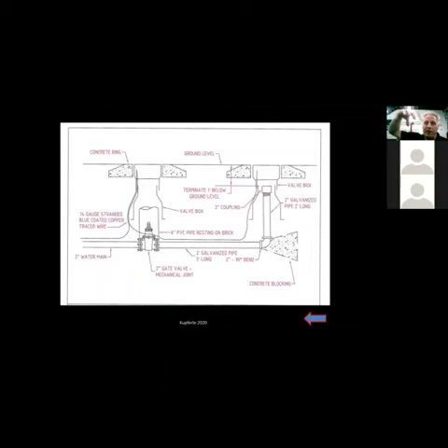But now that I put that TF500 in that valve box, I can leave this gate valve or this curb stop or this ball valve in the open position. I don't use that as my exercising operating mechanism anymore because I have an operating nut on top of this hydrant, on top of this blow off called the TF500. So that means my gate valve, my curb stop, my ball valve is going to last a lot longer because it's going to stay in the open position. The only time I'll ever close that mechanism is when I need to do maintenance on this particular blow off inside the 5.25-inch valve box. And you can put all the guts right from the ground level so you don't even have to do any digging with this one as well.